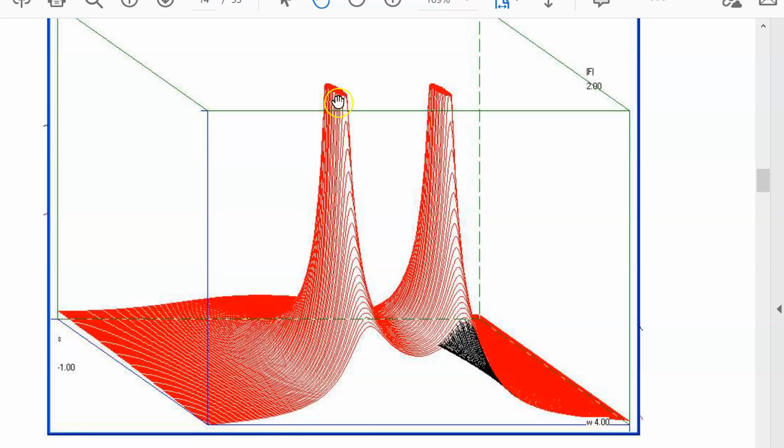And in the background you can see how this filter is designed. Here are 2 poles, here a peg. If you want to have steeper gradients from the passband to the stopband, then add some pegs on the omega axis and we get Cauer filters.